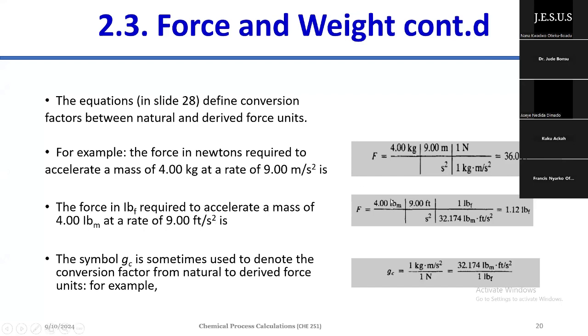You can use that as a conversion factor here. So you are multiplying this with this, and then we want to eliminate all the terms in order to get the pound force standing alone. The 1 pound force is 32.174 pound mass feet per second squared. And I was saying that the per second squared here can come to the top here.